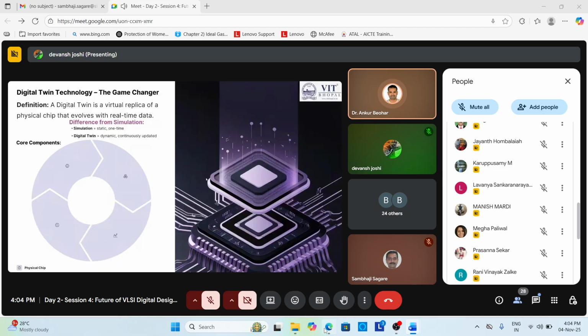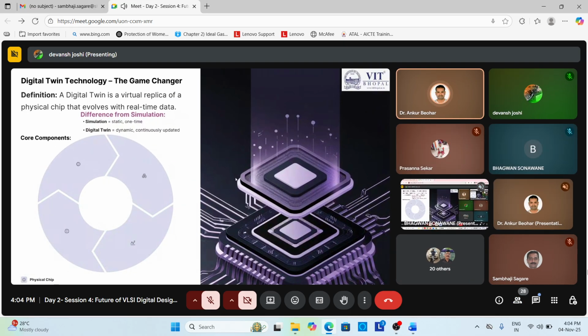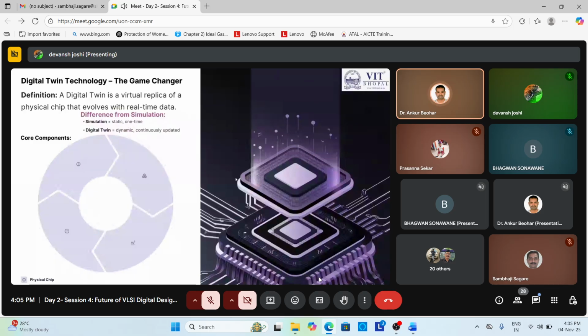And also we have a module of output where we can show major components interaction. So when the architectural design is successfully completed, we have an RTL implementation, that is register transfer level. In the RTL designs, we have hardware description code in Verilog or VHDL, where we describe the data flow between registers using combinational and sequential logic. So this RTL, register transfer level,